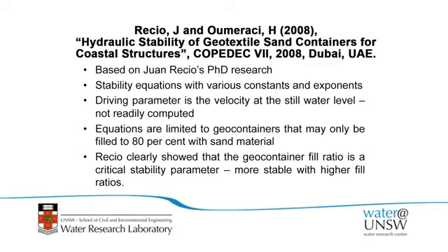So he developed some stability equations as well from his PhD. Some fairly complicated equations though. German practice is to only fill the containers to 80%. So his bags were only filled 80%. Australian practice has been to basically shove as much sand as you can into those bags so that they're filled to 100% capacity. They're filled as tight as they can be. When you only have the 80% filled bags, they get a bit floppy, so that when waves hit them, they tend to flop around a bit more because they're not as constrained by the tensile force of the geotextile.